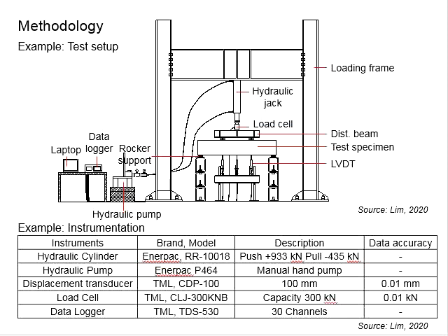It is for you to interpret this vertical displacement into the actual deflections of the beam. You will need to find the correlations between the vertical displacement as measured from the instrument in reference to the distance from the support in order to acquire the deflection profile of the beam at different stages of the loads. And then the simulated condition is simply supported beam.